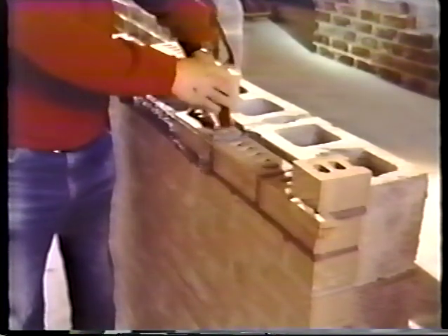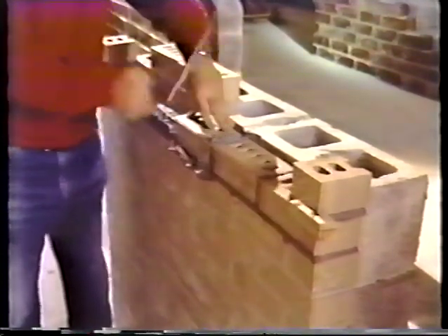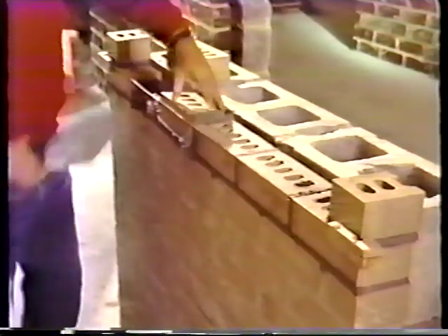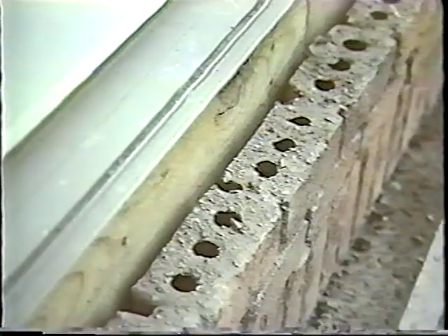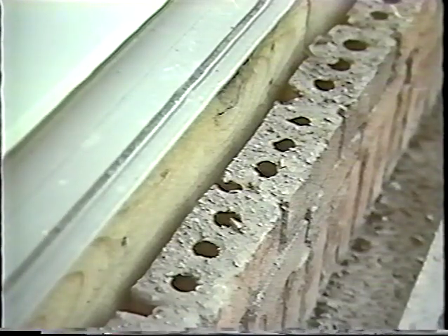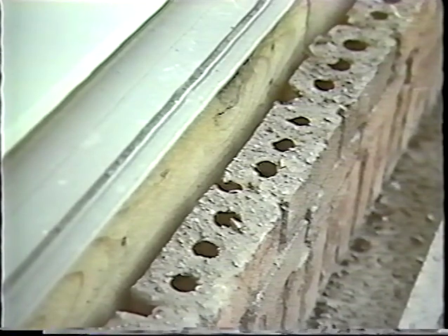Of course, other techniques exist. Many are designed to prevent or correct problems that would happen only occasionally, or they've been developed by the bricklayer or the mason as a personal style. Whatever method is used, the airspace must be kept clear of mortar. In all cases, the bed and head joints should be completely filled with mortar.